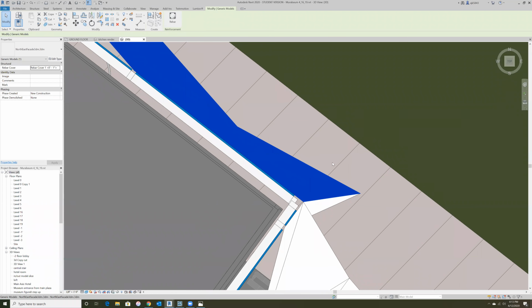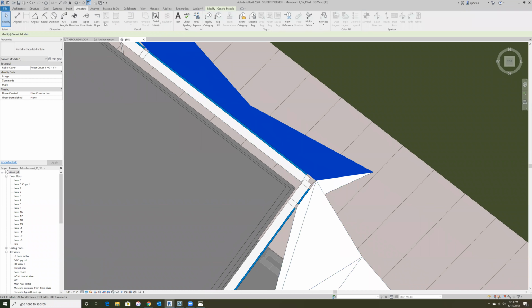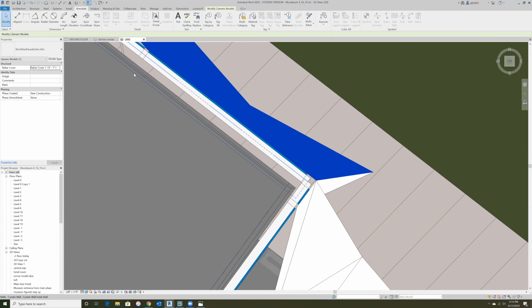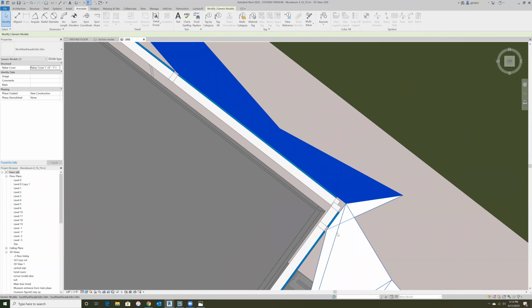The way that I modeled this in Rhino was to draw the perimeter of the building in Revit. Basically, I think I just used some detail lines under the Annotate tab in Revit. And then I copied that out off screen, and I used my file export option and exported those lines as a DWG file. I then opened that DWG file in Rhino and was able to quickly draw the facade based on the extents of the building. So once I knew exactly where my curtain walls would be, I was able to press this facade skin directly up, being able to tie it into that system.